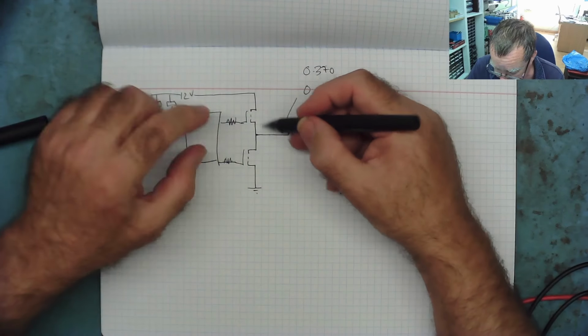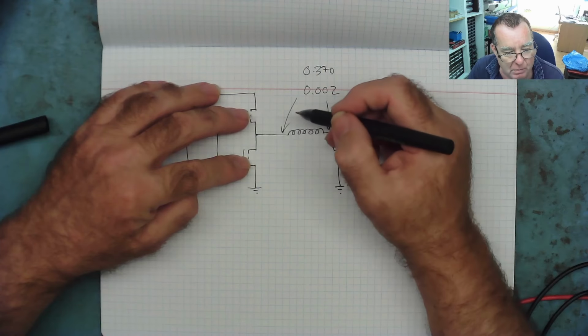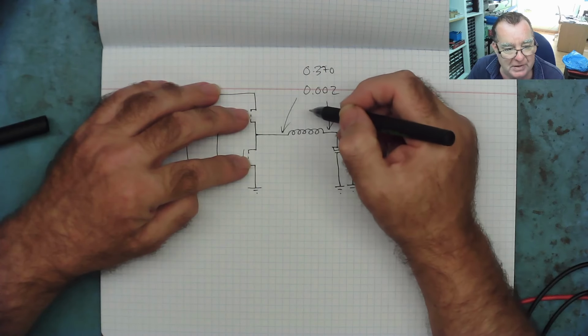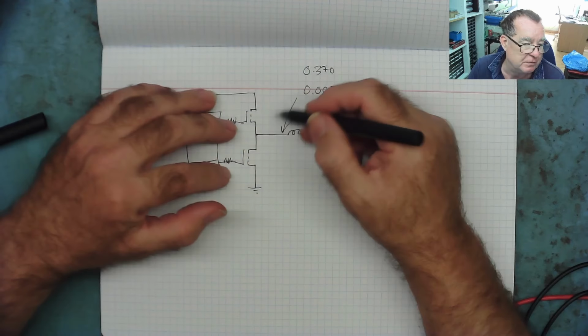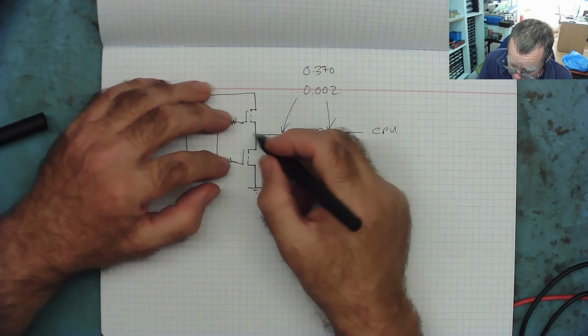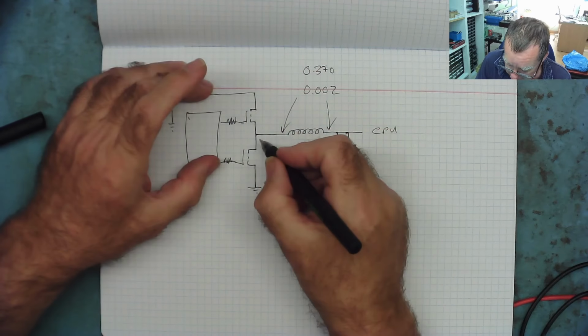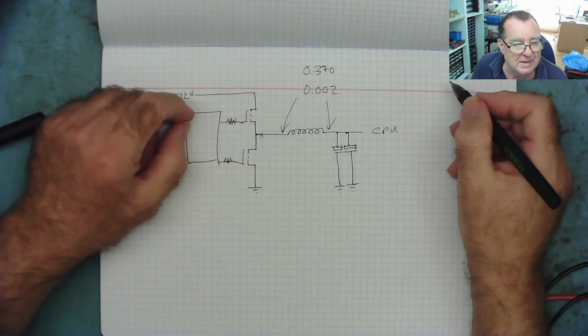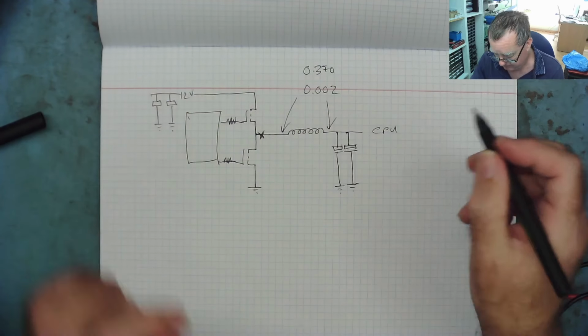In a good circuit, these MOSFETs, to your ESR meter, see a very low voltage, 100 kilohertz signal. It's not enough to make the MOSFETs conduct anyway. They're switched off, there's nothing driving them. So as far as your ESR meter is concerned, on a good phase, that's an open circuit. Nothing can flow that way, yeah?